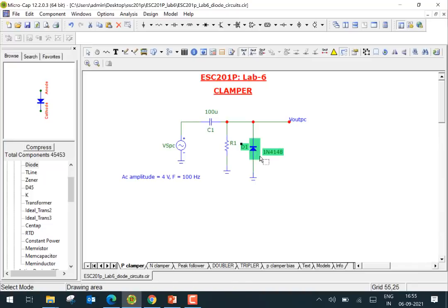The reason we are saying this is that we know a diode conducts in the forward bias direction and does not conduct in the reverse bias. But when you switch a diode, for a brief period, it conducts in the reverse bias. For a brief period, because there is charge stored and diodes have capacitances, so those capacitances have to discharge. That period is related to that parameter called transit time. All these circuits that we are building using diodes rely on the fact that in the reverse bias the diode doesn't conduct, and in the forward bias it allows the current to pass. Anyway, that's about a diode.